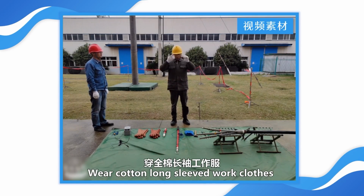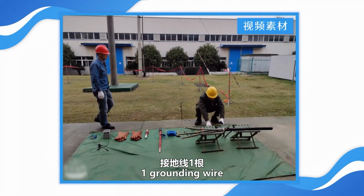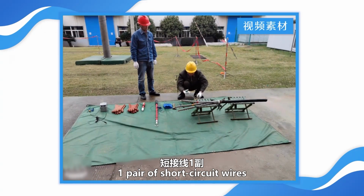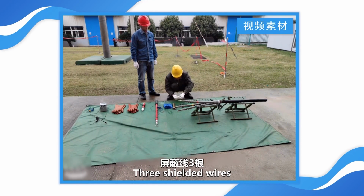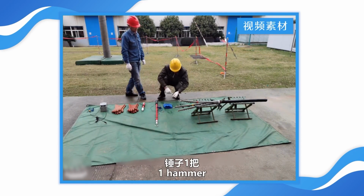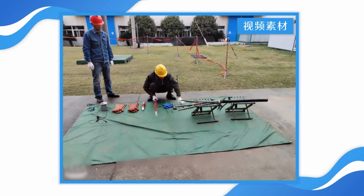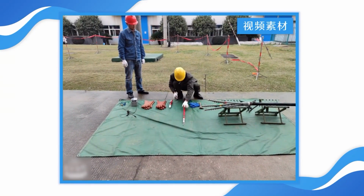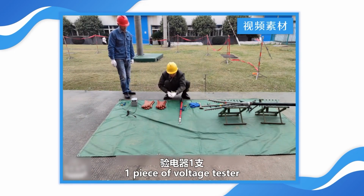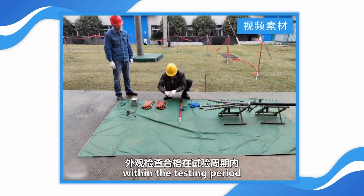Wear cotton long-sleeved work clothes and insulated shoes. Prepare 1 grounding wire, 1 pair of short-circuit wires, 1 pair of pliers, 3 shielded wires, 1 hammer, 1 piece of cloth, 1 discharge rod, and 1 voltage tester. The appearance inspection is qualified within the testing period.